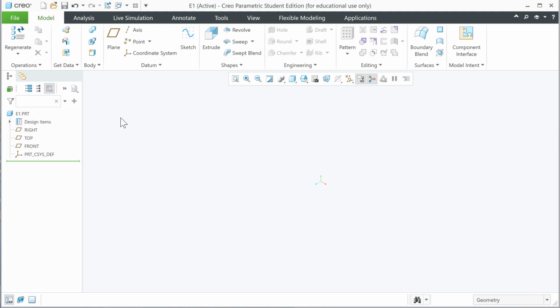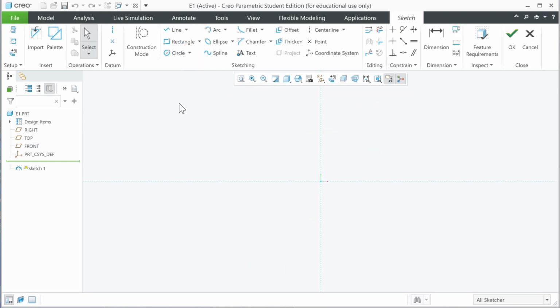All right, so now we'll go ahead and sketch this on the front plane. So you'll see over here on the left, this is our feature tree and our browser, as some people call it, and this is going to contain our roadmap of everything we create, and it allows us to modify and change. So let's go ahead and select front, and right here you have sketch. Now you could go up here as well and find the sketch tool. There it is, right there. Either one is fine. They're the same thing. It's just that sometimes it's easier to just right-click and get these things.